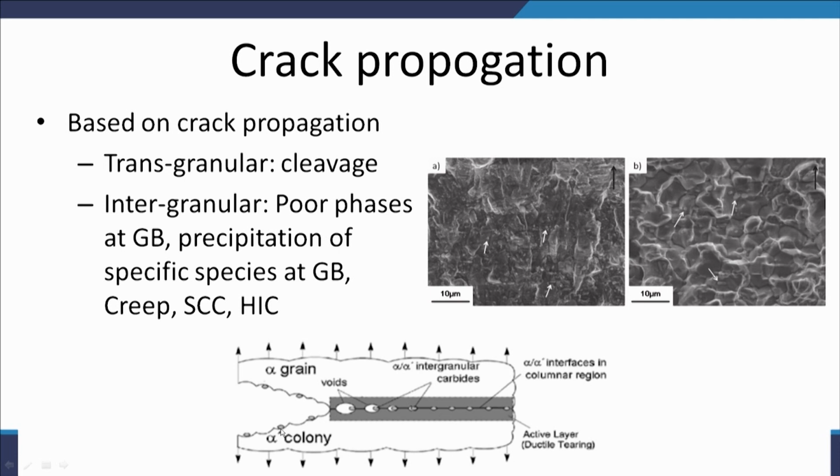facilitated. So, these are shown, these are the second phase particles present at the grain boundary under the influence of external loads. Just ahead of the crack tip, we can find excessive deformation in this area. That deformation will be differential. Of course, the particle will not deform in the same way as the matrix. So, more deformation of the matrix will lead to the formation of voids. The void size will be larger here, and the voids formed here and here are reducing in size, and then the continuous growth will lead to their coalescence and separation.